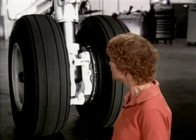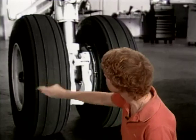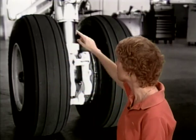Now, what if the tires are underinflated? If the tires are underinflated, not enough pressure, then basically what will be happening is the shoulders of the tire is where the wear is going to show up. You'll have excessive wear in the shoulders of the tires if the tires are underinflated.